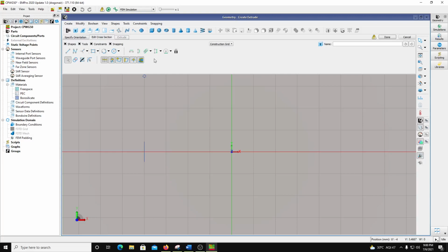And the area has to be totally enclosed to be able to extrude. You cannot take an arc, for example. An arc is not a closed body, so you cannot extrude from an arc. You cannot extrude from something where two areas are overlapping. If you do that, there is a warning which says that you have done something wrong.